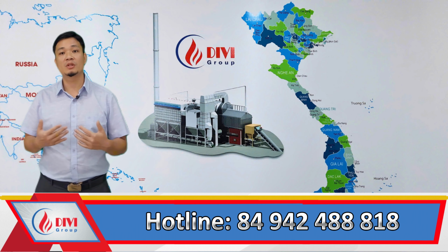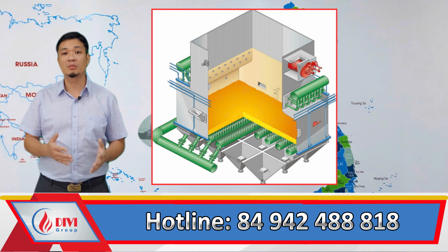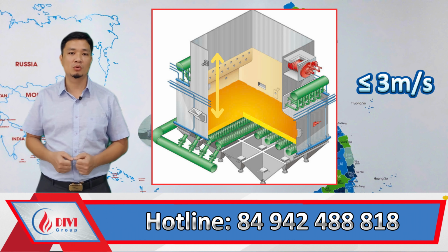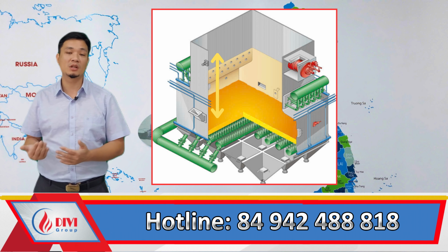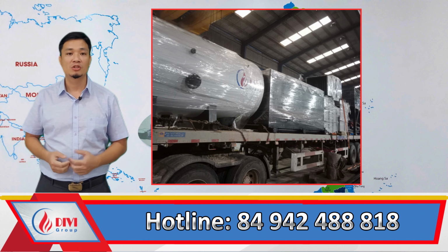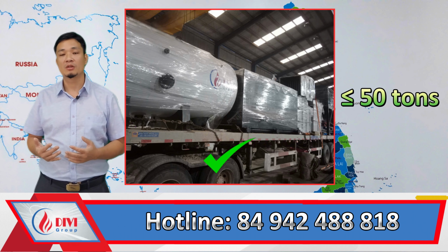Since there is no ash recirculation system in BFB, in order to achieve complete combustion, the flue gas velocity inside the furnace must be kept low to prevent fuel from being carried away. This velocity should not exceed 3 meters per second. Additionally, the furnace height must be sufficient to ensure that the fuel particles remain in the combustion zone for at least 7 seconds. This results in a furnace that is very large in cross-sectional area and height. For large capacity designs, such oversized equipment leads to significant challenges in logistics and transportation. Therefore, BFB boilers are typically limited to under 50 tons per hour, as this allows equipment to remain within transportable dimensions.